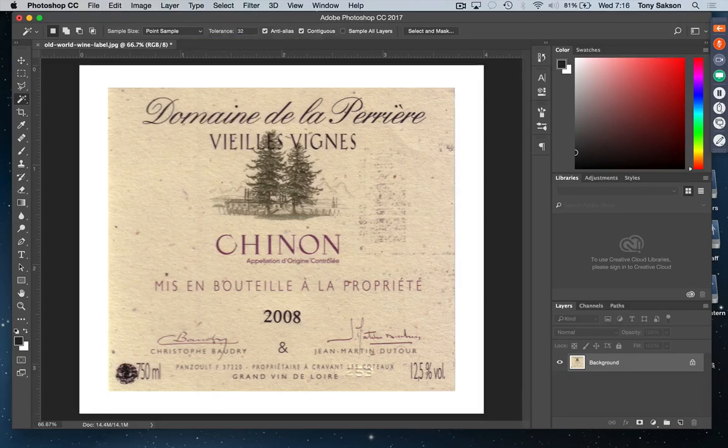So for example, if I select this white pixel here, it will pick surrounding pixels within a 32 range step from pure white to some level of gray. Does that make sense? So it's a range. Now, as I narrow that, the range is not as big and it will not select unwanted pixels.